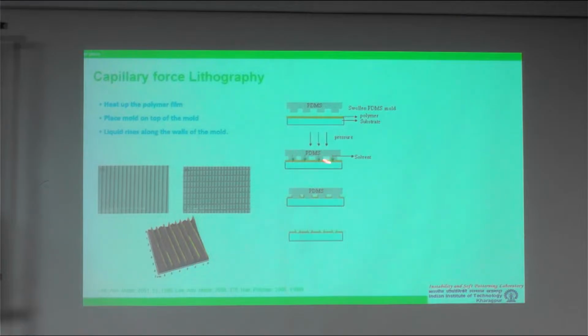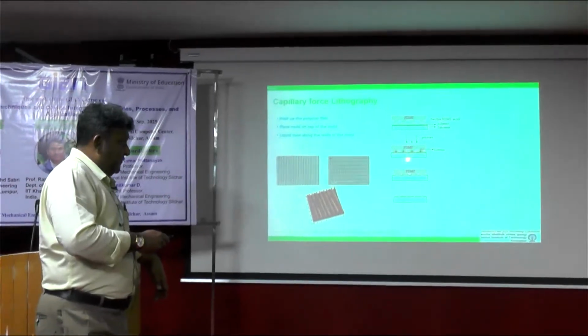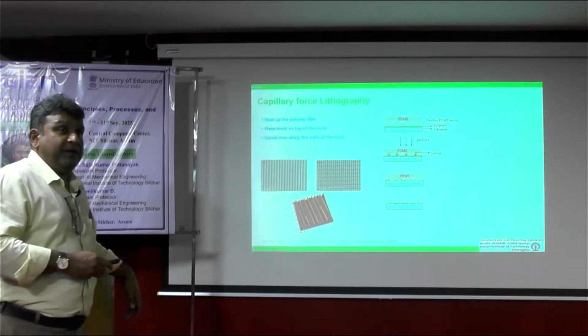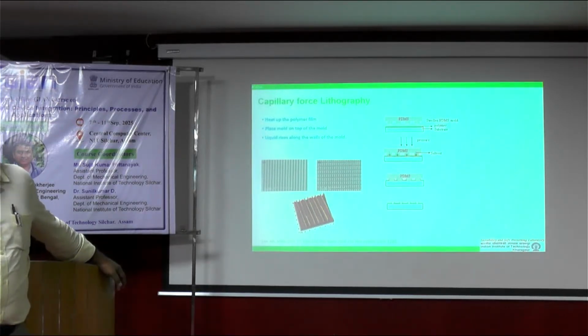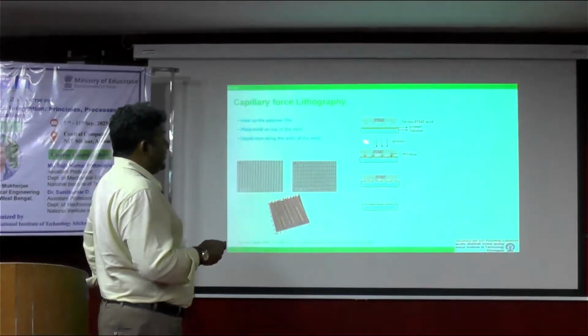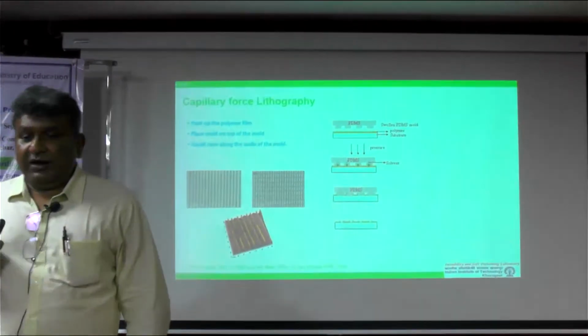If we liquefy the film, then since the stamp is sitting on the film, over the walls of the stamp you can observe a rise of the liquid meniscus due to capillary action, right? So basically, if you give adequate time, there is complete mold filling by capillarity. Now, what is the advantage?